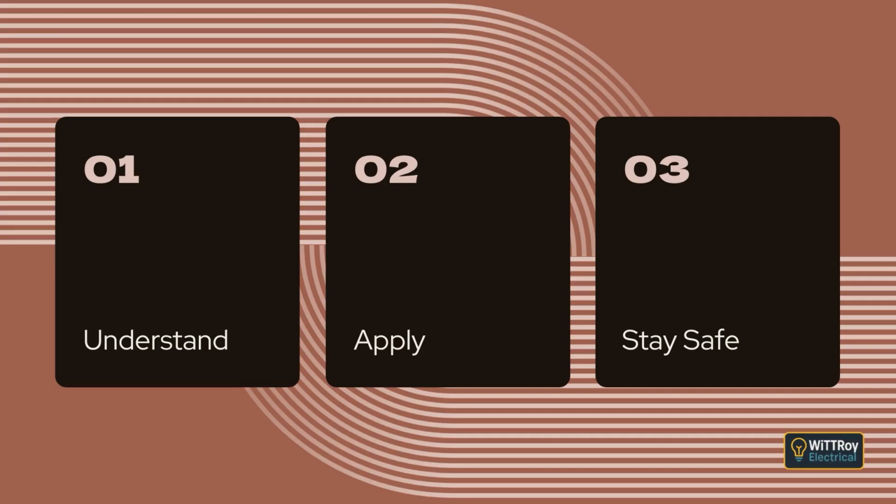Clause 3.9.7, Particular requirements. This clause sets out additional installation requirements for specific wiring systems. Clause 3.9.7.1, Consumers' mains. Consumers' mains must be installed so the risk of short circuit is kept as low as possible. Clause 3.9.7.1.1, Protected. Where consumers' mains are protected on the supply side by a short circuit protective device, they must comply with all the relevant requirements of this section. Sometimes the electricity distributor's protective devices already provide this protection.